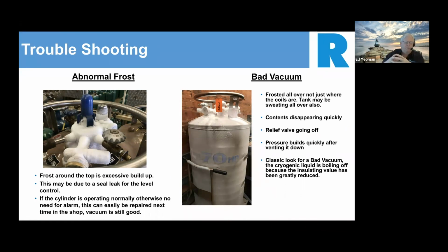So that could be a leak there, and you could just operate the cylinder as normal, and the next time it's empty, have your team pull the float rod, replace that O-ring, reset it and see if that makes the problem go away.